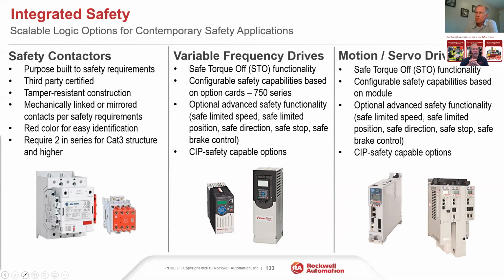There are also products that have advanced functions within the product itself, safe limited speed, safe limited position, direction, acceleration, stop, brake control, etc. And there are methods to do that kind of within the drive and only in the drive, but there are also methods to do that all over the network and leveraging logics and that safety encoder that we talked about earlier.